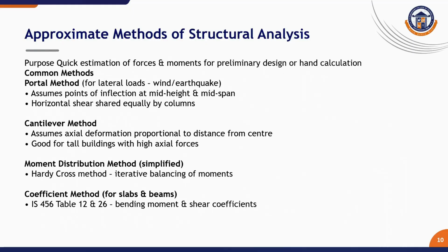Design steps. Determine area equal to total load divided by safe bearing capacity of the soil. Locate center of gravity of the load equal to center of footing. Assume dimensions, length and width. Check soil pressure, uniform or trapezoidal. Design as longitudinal transverse beams. Provide reinforcement for bending and shear. Check development length and anchorage.